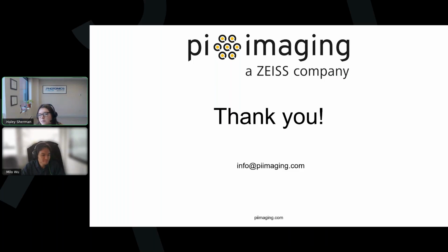The first question I have is, can you clarify what you mean by exposure time and integration? With a SPAD, are you summing across multiple frames to get an integration, where a single bit frame is an exposure? Yes, it's a different term, but it means the same thing. Let's say if you're using a camera, the total integration time of an 8-bit image consists of 255 1-bit images, and the total integration time is the sum of all those 255 1-bit images' exposure times. So it's the same concept.